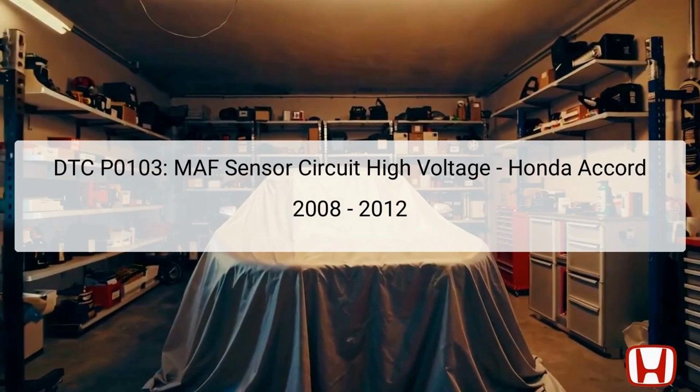The Diagnostic Trouble Code, DTC P0103, indicates a high voltage signal in the mass airflow MAF sensor circuit of the 2008 to 2012 Honda Accord. The MAF sensor is crucial for measuring the volume of air entering the engine, which helps the Engine Control Module, ECM, or Powertrain Control Module, PCM, adjust the fuel-to-air ratio for optimal engine performance.